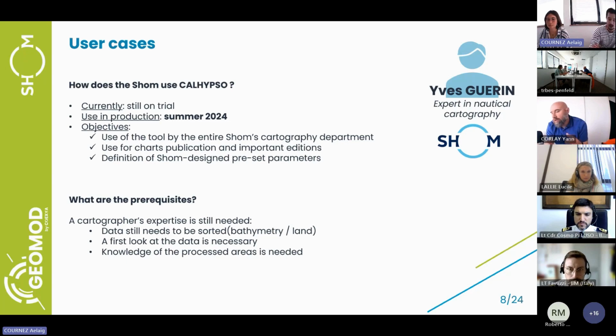Following this action, the cartographer must be aware of what he wants to obtain: what density of soundings they want based on depth of the surveyed area, which smoothing for curves, display scale, etc. This is an important point since otherwise the outputs may not be satisfactory or suited to the needs, as for traditional manual or digital charting.